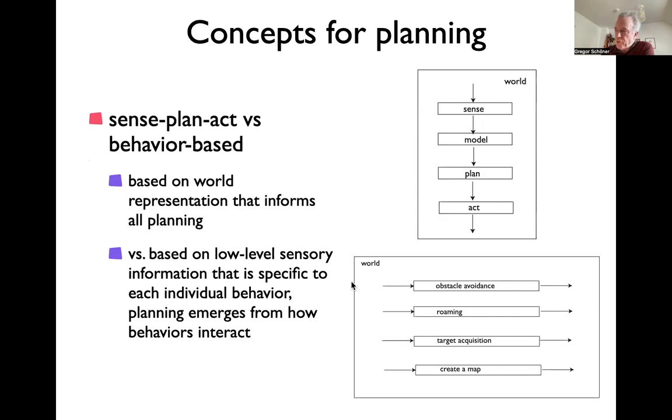While the strict behavior-based idea would be that every constraint would have its own sensory input-output function. So like obstacle avoidance versus target acquisition would have their own sensory paths. And in the examples I gave you for the so-called subsymbolic approach, that is well approximated as a behavior-based system here in this bottom sense. And the combination of the different constraints was simply by superposing the contributions to the vector field. And I'll show you today another example, and it goes in this direction.